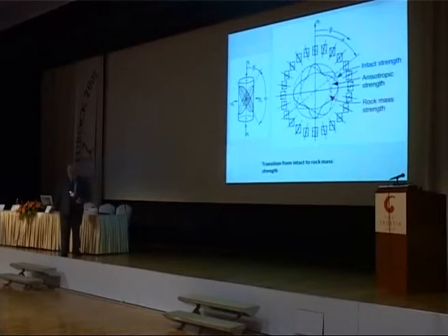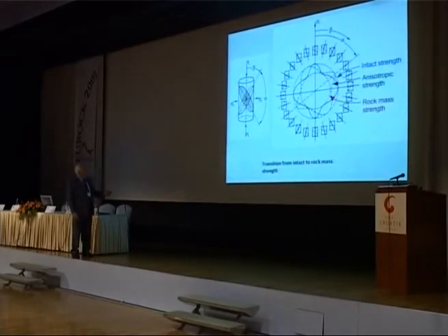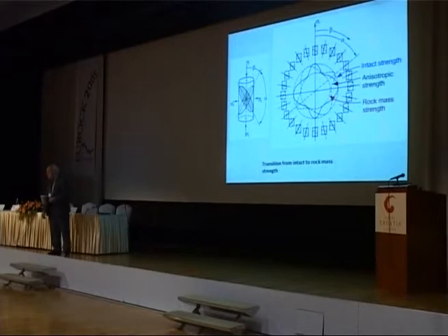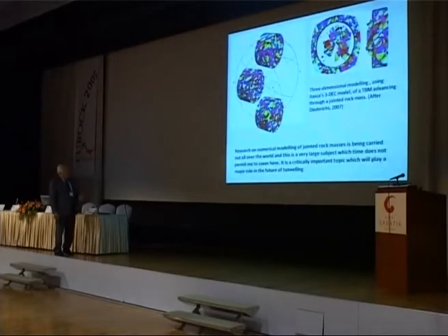If we look at the transition from massive rock to jointed and heavily jointed rock, we go through a process whereby adding one joint set, we end up with a highly anisotropic system. Two joint sets evens it out a bit, and many joint sets make it a pseudo-homogeneous material. But this area where you have relatively few joints can be enormously important in some aspects of engineering.